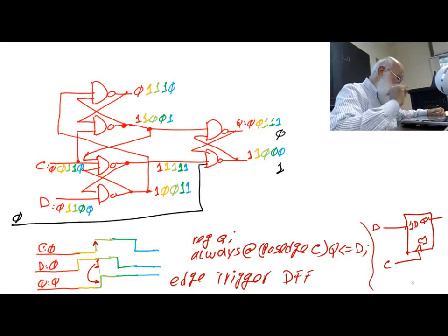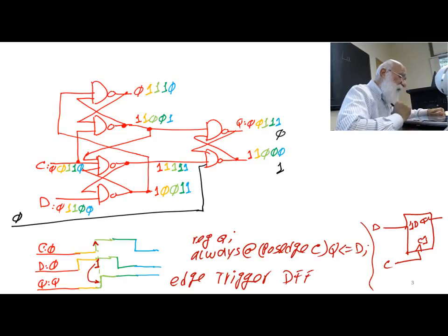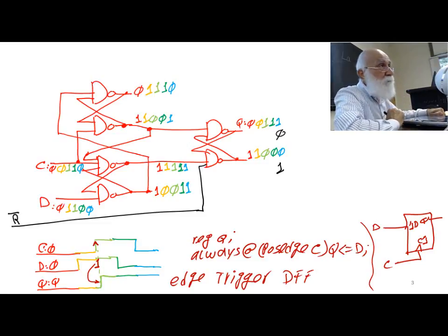Okay, so I just added the signal, but there is a problem with it. I just added the signal to the circuit that forces my output to reset to 0, but that happens when it is 0. So I call this one active low reset. It is an active low reset.